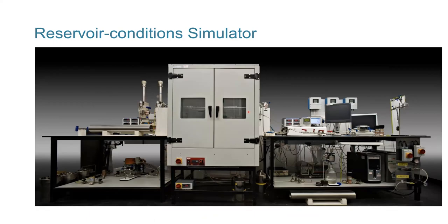So this is a typical piece of high-tech reservoir kit. The general philosophy behind formation damage testing, lab simulations, whatever you want to call this, is to take a real piece of reservoir rock if it's available, or if not, take an analog or representative piece of material, and put it to the correct near wellbore temperature and pressure conditions. So this is a test rig, oven, air bath, whatever you want to call it. Inside here we have a core sample in a core holder.